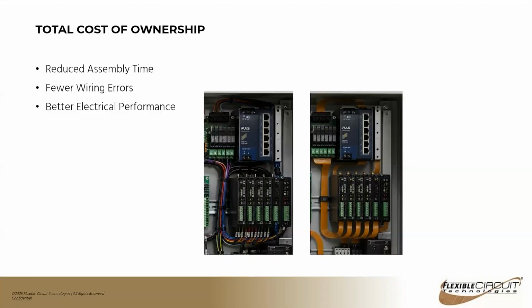And then better electrical performance. Flexible circuits lend themselves very well to great electrical performance because the conductor width is very consistent. The space from conductor to conductor is very consistent. And as you start adding layers of material, the dielectric between your signal layers and your shield layers is very consistent as well. So generally, it's just a much better electrical performance.